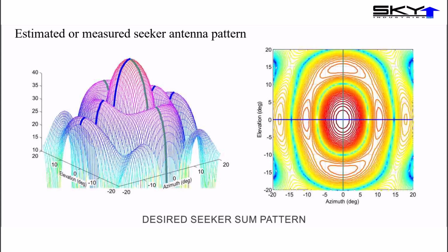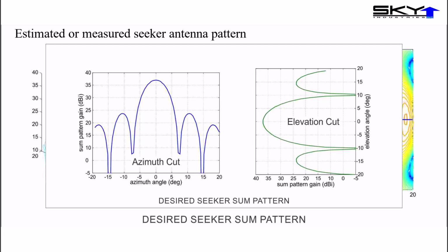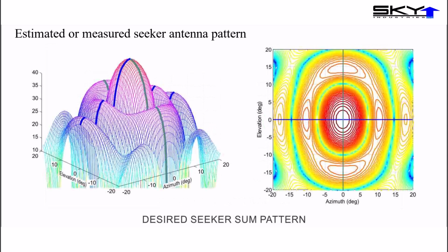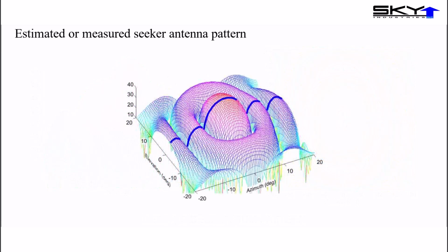The two-dimensional azimuth elevation pattern must be synthesized by blending the azimuth cut and the elevation cut of the antenna patterns to calculate the gains at intermediate angles which don't lie exactly on the azimuth cut or the elevation cut. The correct way to do this is by circularly blending the azimuth and elevation patterns, but this requires a bit of math, not much, but some.